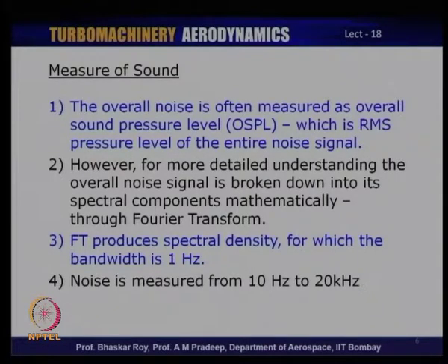The more detailed understanding of the overall noise signal is then broken into what is known as spectral components using certain mathematical formats, and this is of course done through Fourier transform, which is typically used in many wave measurements, various kinds of measurement of various waves, and sound being a waveform, it is also captured in Fourier transform. Now, Fourier transform produces spectral density, for which the standard bandwidth is 1 hertz.